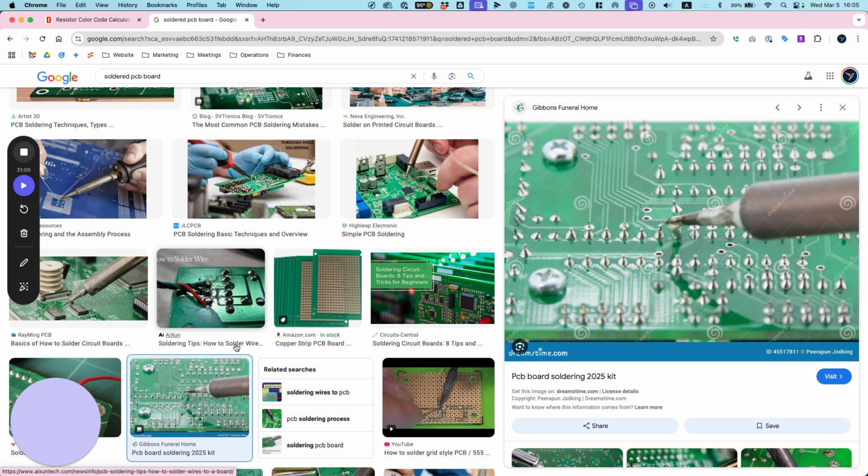So if that's the case, even though this thing says it's a 14.8 volt battery, when you charge up a 4S battery, you're going to get 4.2 volts per cell. You have 4 cells. What is the actual voltage going to end up being when you measure this?